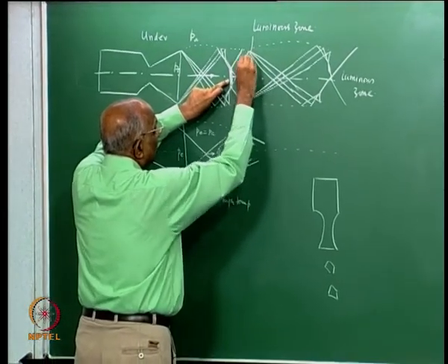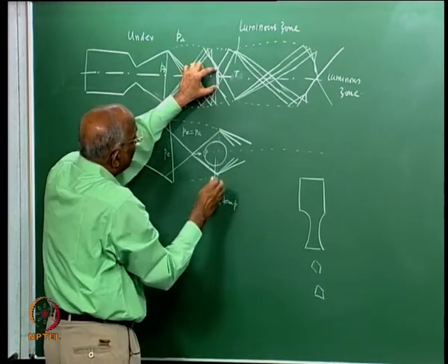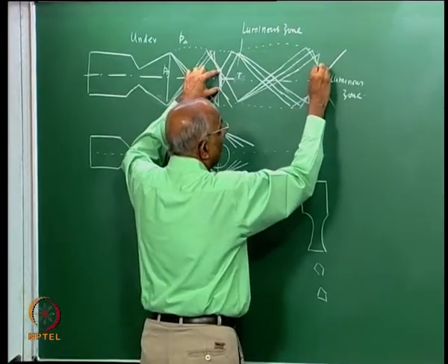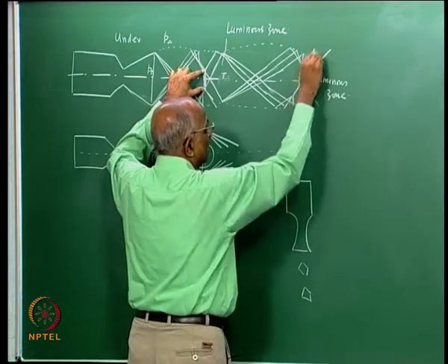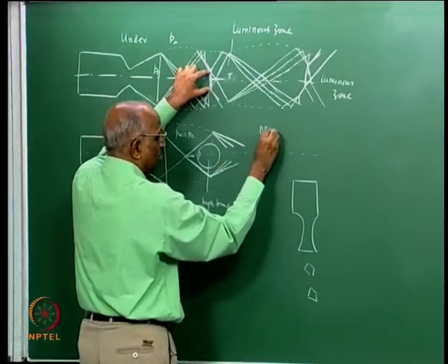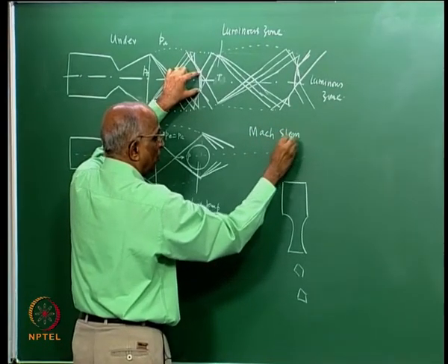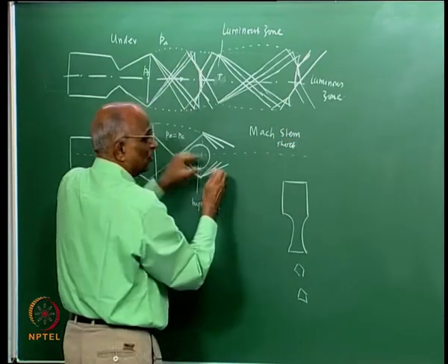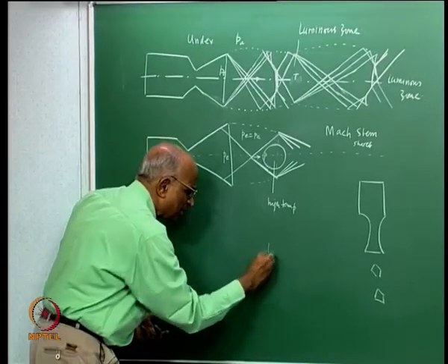The shock pattern therefore continually changes, and you have a shock structure forming over here. Similarly, I will have a shock structure getting formed like this. That is, the simplified picture gets a little complicated because I have a Mach stem shock formed, and that is how you see the diamonds in those particular pictures. The diamond pattern is actually something like this.